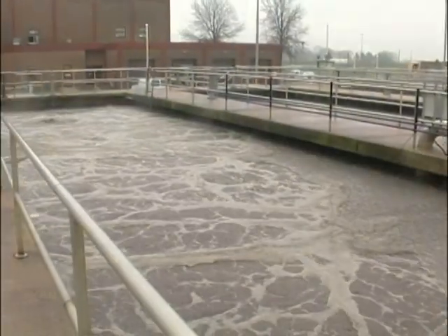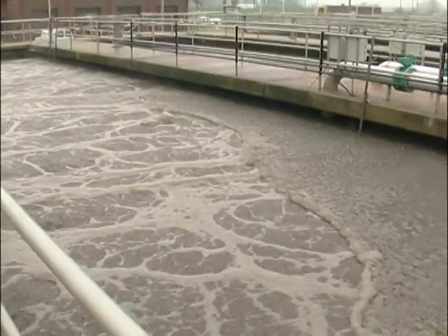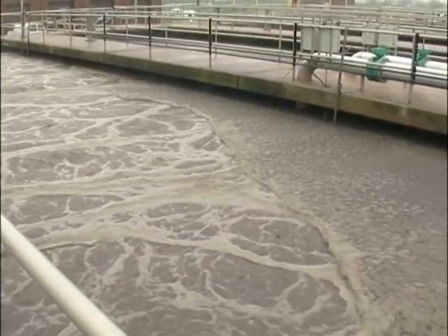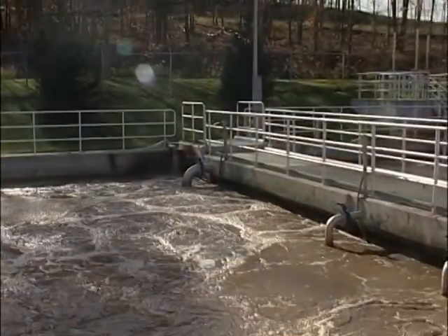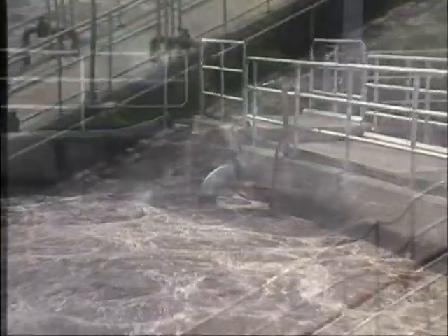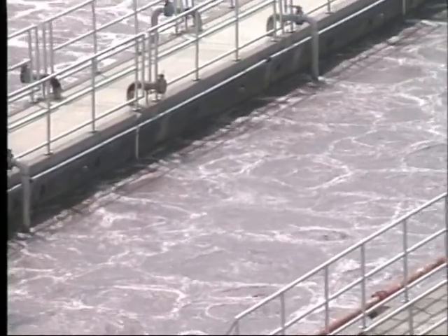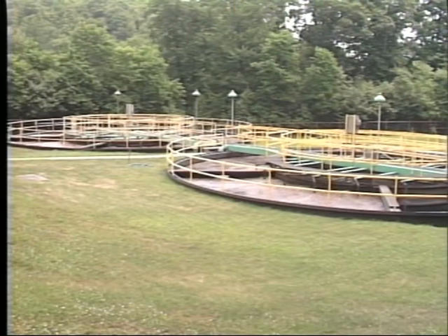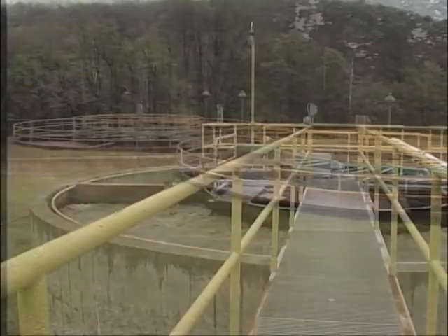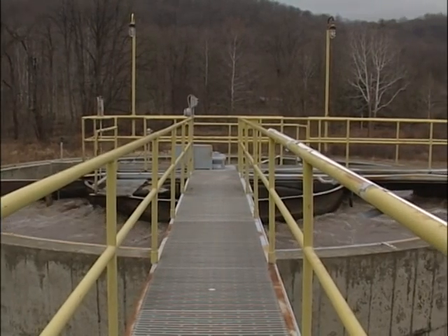In the activated sludge process, the extended aeration configuration works well in achieving nitrification and can typically be easily retrofitted to achieve denitrification as well. The long MCRTs provided in the extended aeration process work well for growing nitrifying organisms. The least capable in terms of activated sludge for achieving nitrification would be the contact stabilization process. However, many contact stabilization facilities do indeed nitrify.